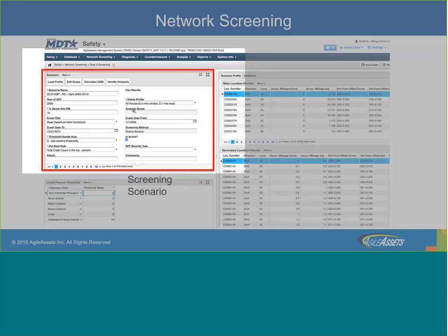So in this case, I'm running a profile that is statewide for all routes, and the route is divided into a 0.1 mile window and 0.1 mile step. In the Highway Safety Manual, we have a sliding window technique that you can use to dissect the route into smaller segments, and within one segment you can run a moving window to scan the network and identify if there is an issue or not.